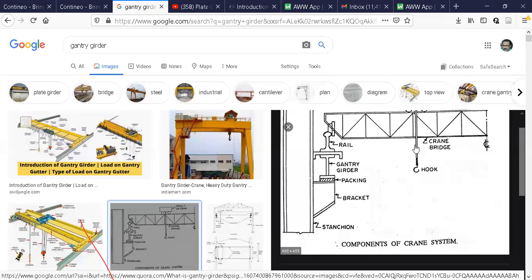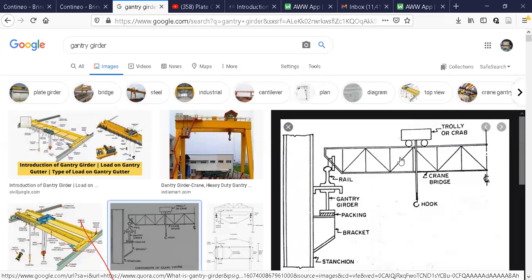The load is not stationary here. The load is moving continuously. For which position of the loads will the maximum bending moment occur? So it is all about your influence line diagram. We have studied in the analysis of determinate structures influence line diagrams for bending moment, and influence line diagrams for reactions and shear forces. So that is what you make use of in this particular problem. Influence line diagram means for what position of the loads there is a maximum bending moment at a particular point, because the loads are constantly moving.